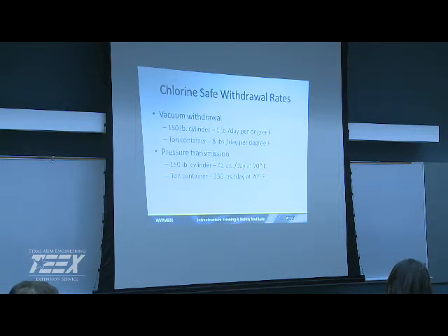So we do need to keep our chlorinator rooms up at a certain temperature. Texas, we don't have a whole lot of problems, especially down south. We can pull some gas like crazy. But when you're up north, if you are using 150s or something like that, you do need to have a heated room. Okay, you're not going to get any out on cold days.